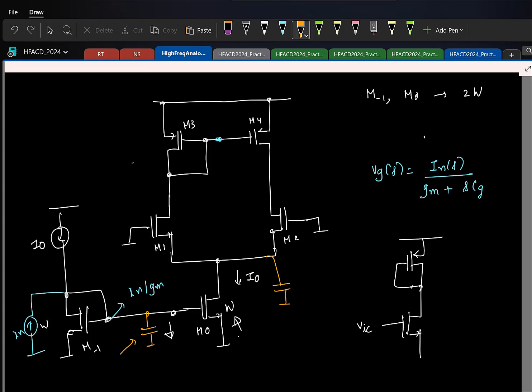But now if I have a capacitor there, at high frequencies the capacitor will indeed provide a path. So the op amp will start to respond to common mode signals. So if we have a large capacitor at the tail node, this will impact your high frequency common mode response, CMR. Right?